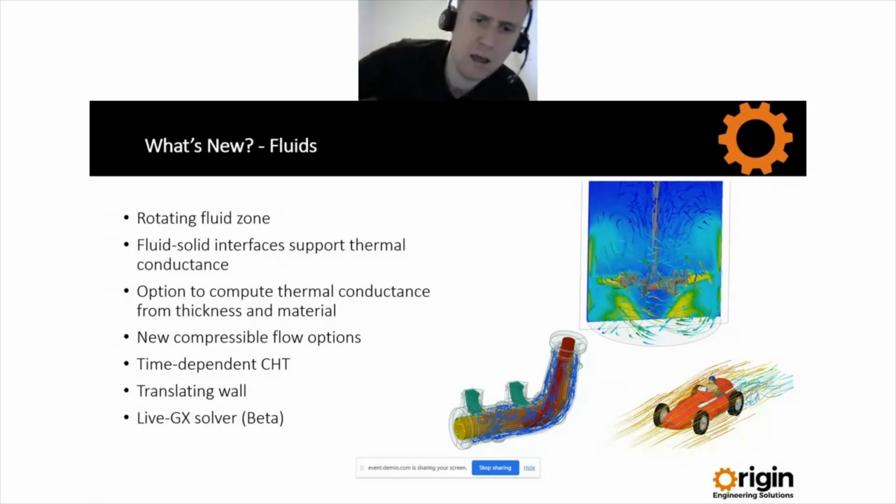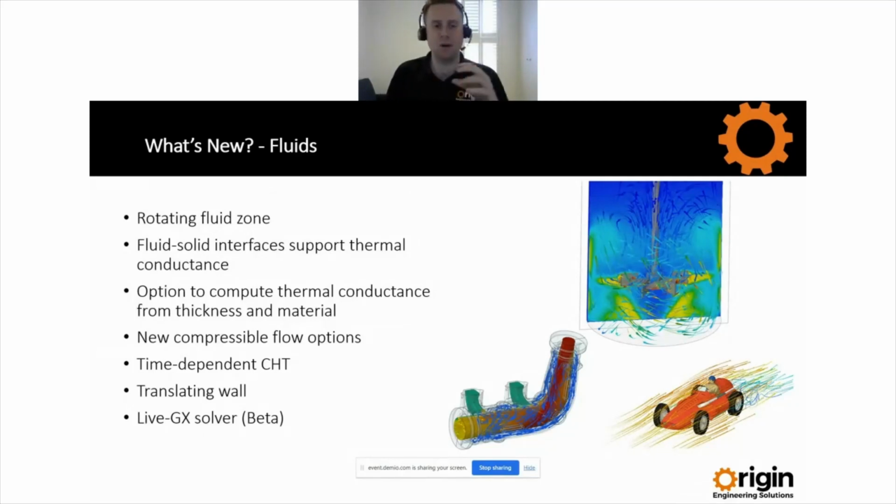One of the most interesting developments as far as we're concerned is this: today we've focused a lot on the explore mode, which is where it's using the graphics card to solve the simulation, and it meshes it for you in the background, so you don't have so much control over that mesh. There is another mode which I alluded to in the presentation, which is a refine mode, which is the idea of deciding on the mesh for yourself.